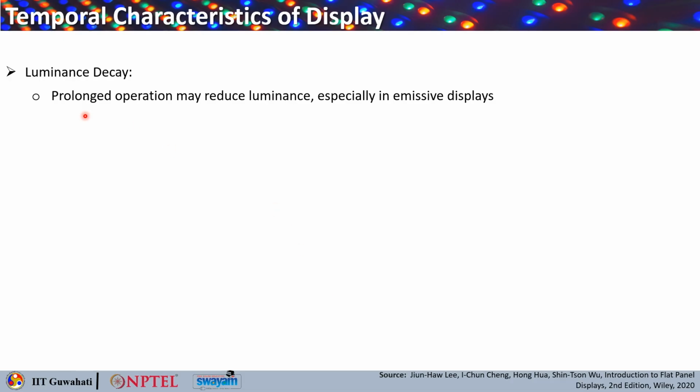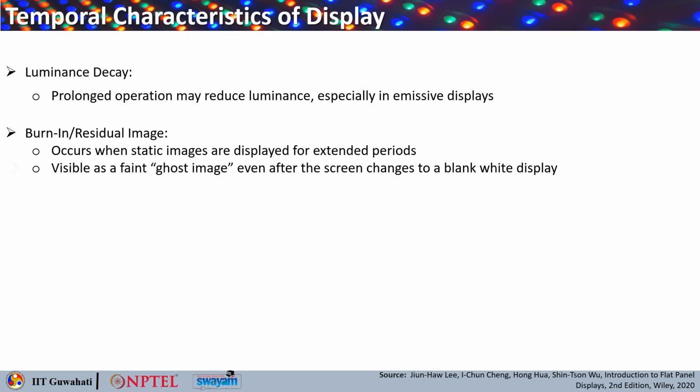Another important characteristic is the luminance decay. Whenever there is prolonged operation of a display, this may reduce luminance, and especially this can happen in the case of emissive displays. Other issues may also come up, something like burn-in or residual image, which is the case for OLEDs. I was telling you about the problem in OLED TVs.